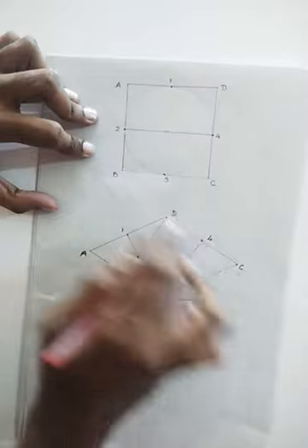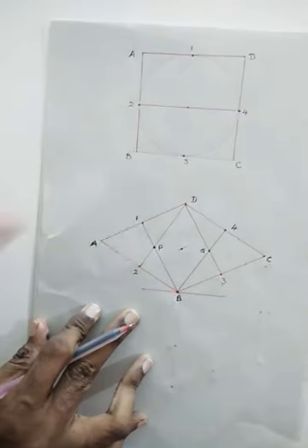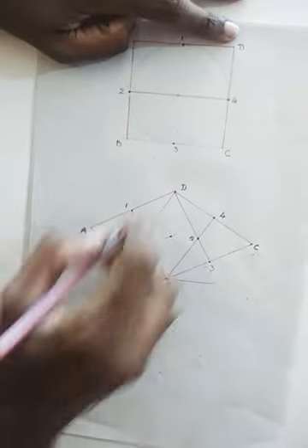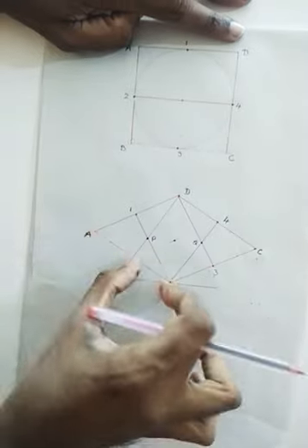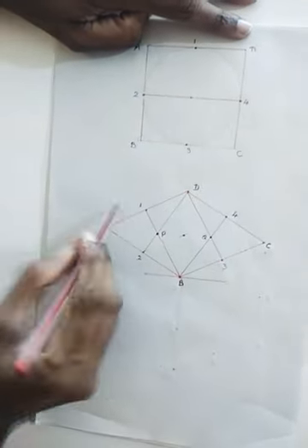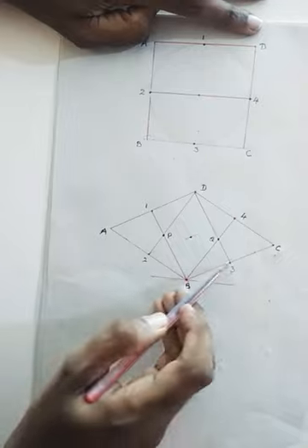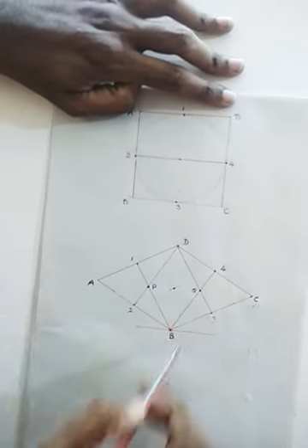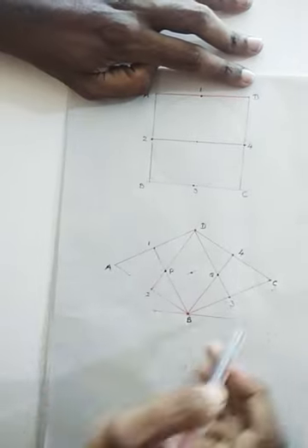So first I will be drawing this box. It is a square. You can take the same radius and mark it on all 4 sides. Now, after that, you identify the midpoints also. We have marked the midpoints here. You take this distance and transfer it, but make sure it is the exact midpoint. When we are finding the midpoints, we will be getting points 1, 2, 3 and 4. So what I did was, I first marked A, B, C, D, identified this box, then identified the midpoints 1, 2, 3, 4.